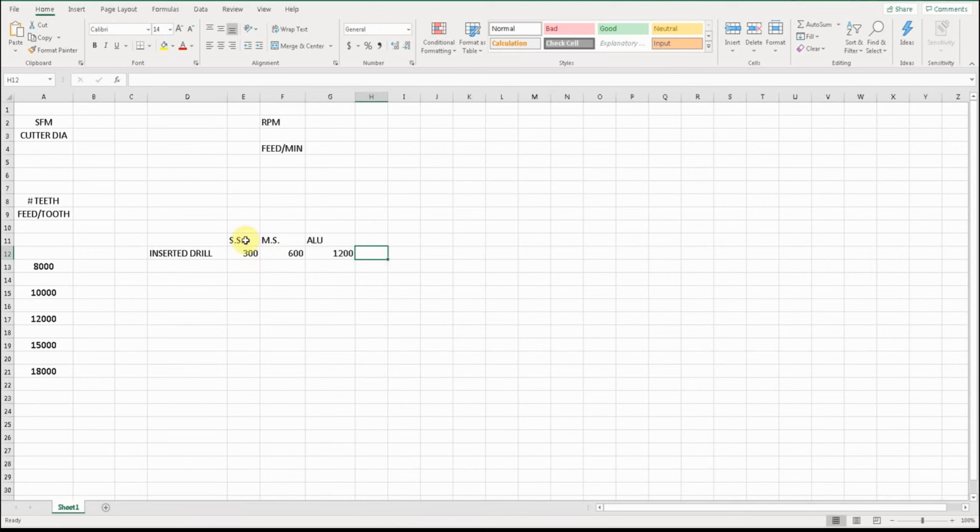So these are good for your stainless. It's your 303, 304. These stainless numbers will work. Mild steel, 1018, something like that will work. These numbers will all be good for your aluminum, 6061, 6063. These are a good starting point for your numbers. If you're unsure, you can look at this and say, okay, I know these numbers are going to work. And if you have certain inserts you use, like in stainless, they've got some inserts that they recommend to run at 500 surface foot.